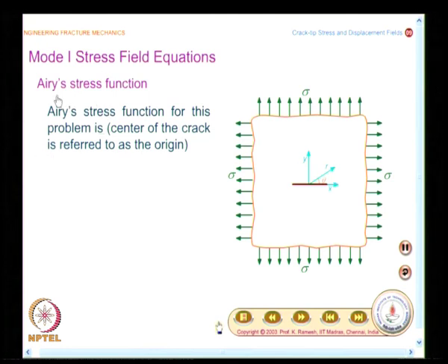This is again something new. You have a function, the function is expressed in terms of r comma theta, but it is actually giving Cartesian stress components. And what is the stress function which was used, which is constructed based on the Westergaard stress function? It was phi equal to real part of z double bar plus y imaginary part of z bar. See, in all our development, if I have a problem, once the stress function is specified, everything about the problem is known.